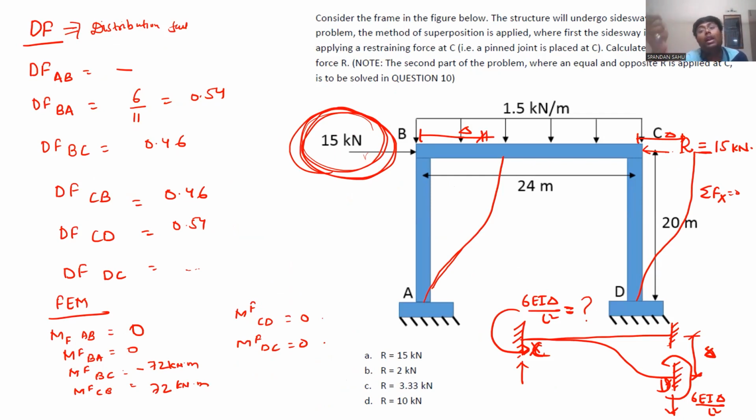But how much reaction is actually needed, such that for your real case and what you have assumed, your moment will be the same? If your reaction R dash had been 15 kilonewton, then whatever fixed end moment you assumed would have been correct. But due to the assumption of 100 kilonewton, you got R dash to be 13.42. But you need 15 kilonewton.